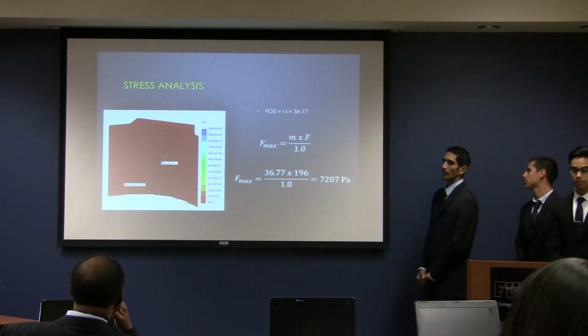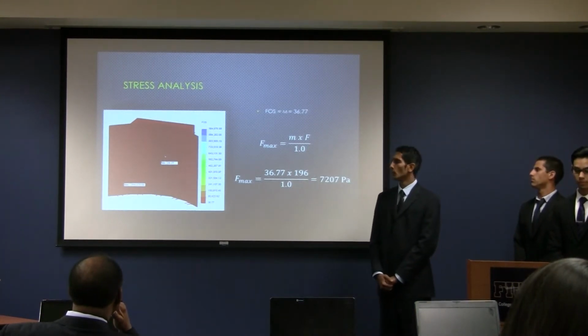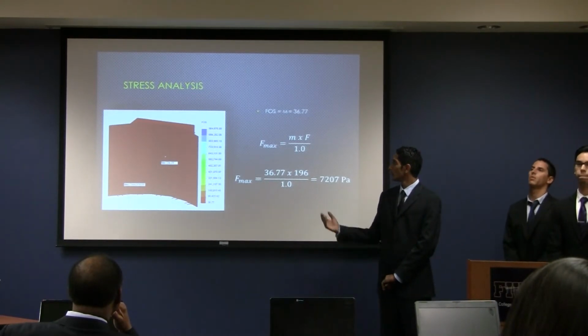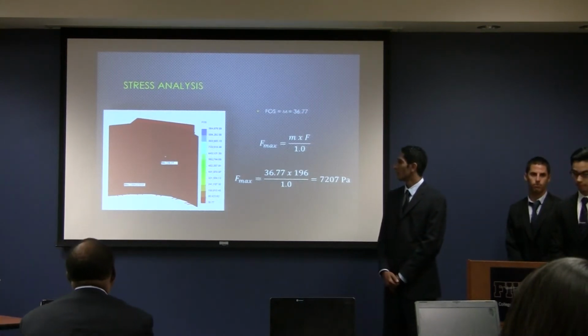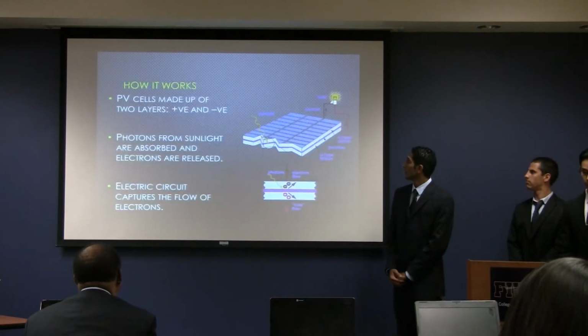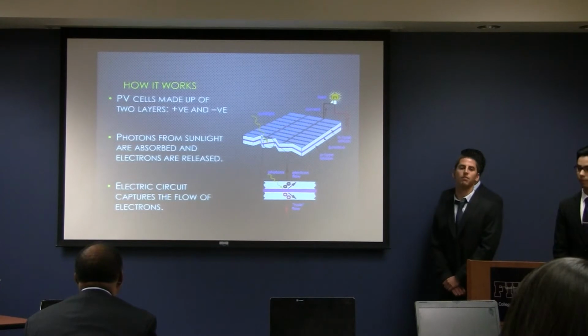We did a stress analysis of our design, and by using a 50 miles per hour wind speed, we proved the strength and the safety of the design. The simulation shows it can withstand the maximum pressure of 7.2 kilopascals, which is pretty safe and can withstand hurricane conditions.